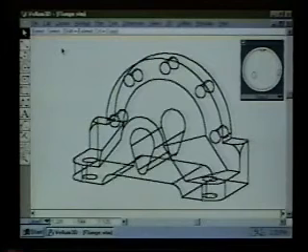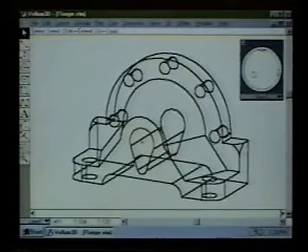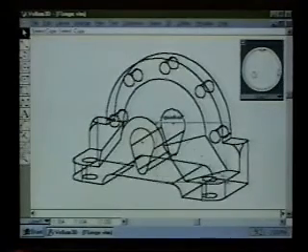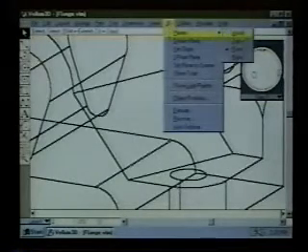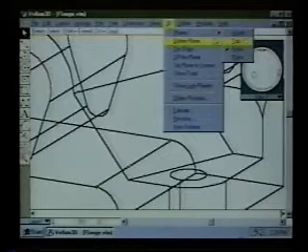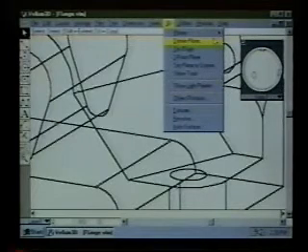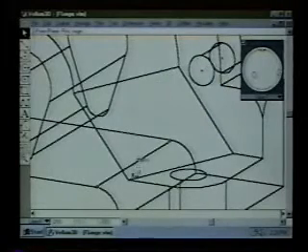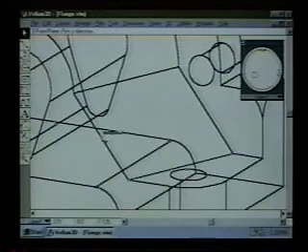And then one final thing that we'll do here is put something on this sloped face. How do you handle a non-orthogonal plane? We've drawn things on the top plane, and we've drawn things on the front plane, but what about an odd plane like this? Well, it's actually quite simple. I'm going to zoom in here. I have my normal planes here, but none of these work, so I need to define a new plane. But there's actually even an easier way. I can say 3-point plane, because I know 3 points, don't I? There's 1 point, there's a second point, and then anywhere along here it would be a third point.